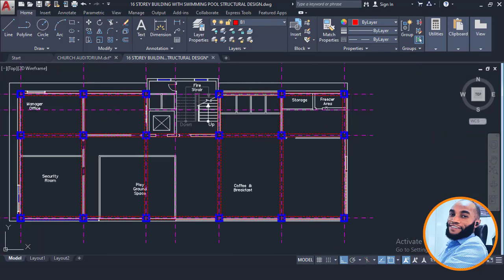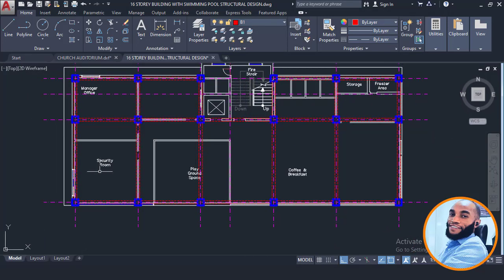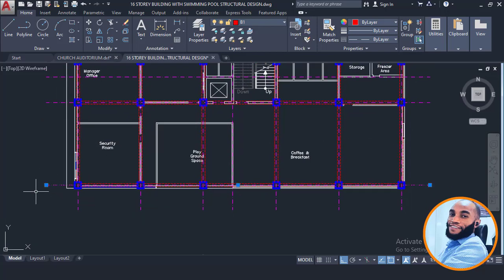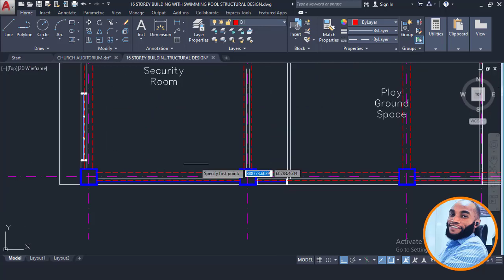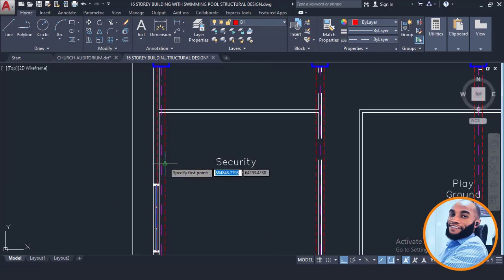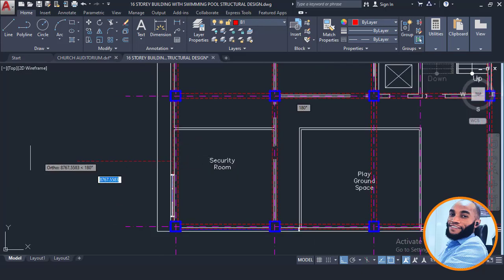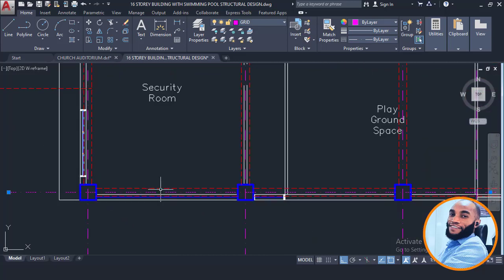That's fine. So all these panels now are okay within the slab area, but this other one here is not okay. So I'll have to provide an intermediate beam, or let me see, yes, basically around this place here. So I'll quickly click at this grid line here, and then click on the column points here. But first of all, let me find the center point of this place here, because I want the beam to run at the center. So this is the center point here. So I'll quickly come here, click a line here, and copy this now, and copy all the beams around this place here.